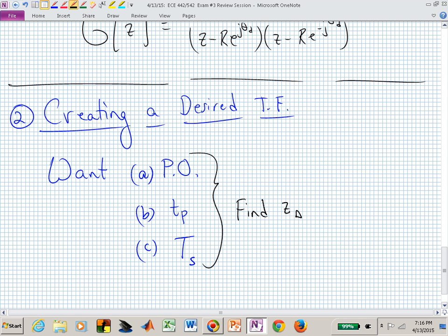What does the percent overshoot tell you? What information does that provide? Or if I say percent overshoot, what else are you pairing with percent overshoot? The squiggle, the zeta, the damping ratio. This is now zeta. What's time to peak providing? Or what are you connecting with that? That's now the angle. Settling time is now the radius,